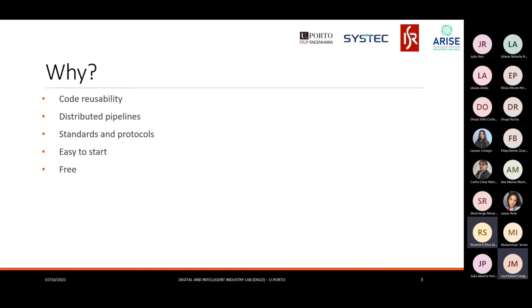Function blocks that were mentioned in the previous slide eliminate that problem. You create those function blocks, they are the code that you decided them to be, and then you can easily connect them to other function blocks, rearrange them however you want, eliminate them, add new ones, and it's much easier to reuse code this way.